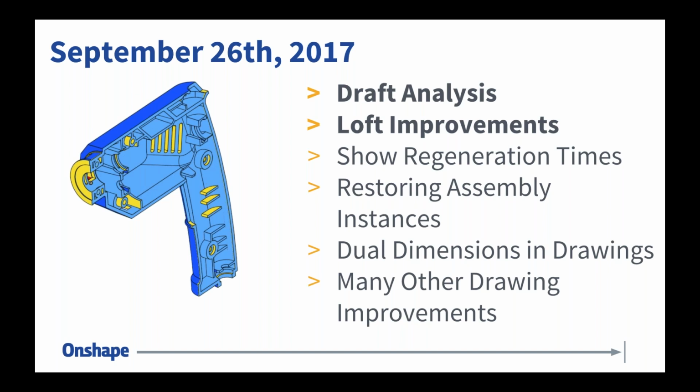September 26th, I think the biggest improvement in this update was definitely draft analysis. Draft analysis is something that a lot of users have requested. If you do any kind of work with drafted faces, things like injection molded parts or cast parts where draft is especially important for parts to be released from a mold, for example, then draft analysis is a critical feature for you.